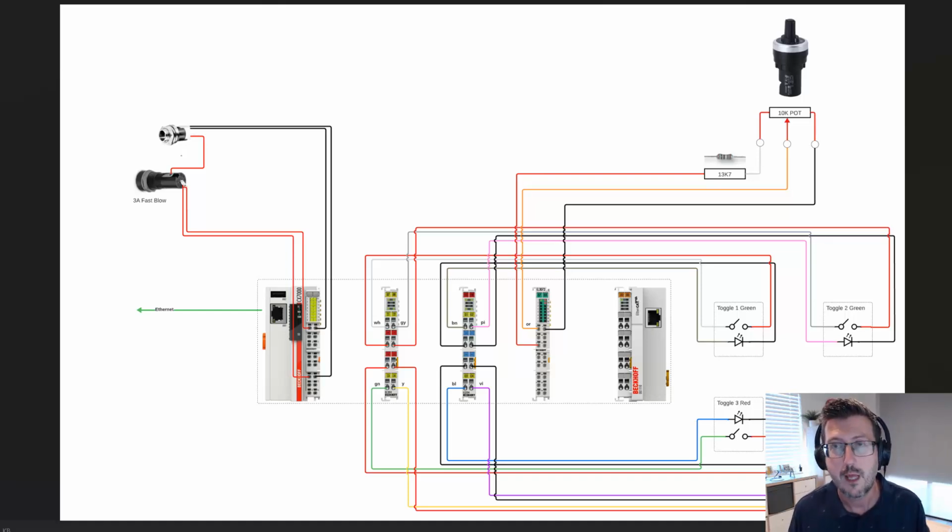License-wise, when we interact with the I/O side of things, you've got TwinCAT ADS, which is free of charge. TwinCAT IO is free of charge up to a certain performance level anyway. And then you've got TwinCAT PLC over the top of that. We don't need the PLC license. The other nice thing with the CX7000 is all licenses are included. So everything we're going to do now is already included when you buy a CX7000. If you were to buy the CX8190, for example, at that performance level, you're not going to be paying for I/O. It's only when you need the PLC license that has a cost associated with it. Otherwise, I/O is free to use. You just buy the hardware.